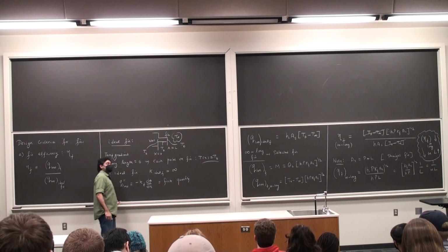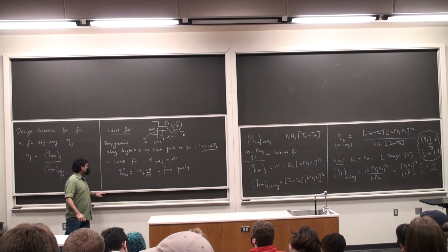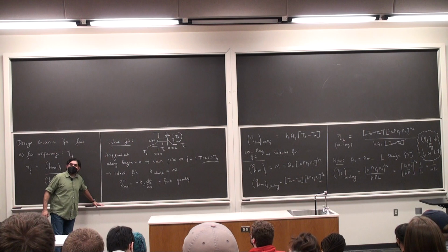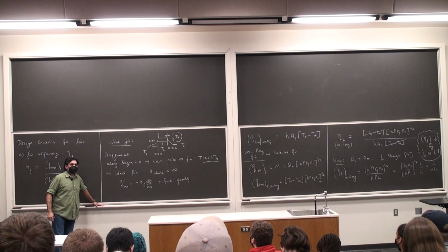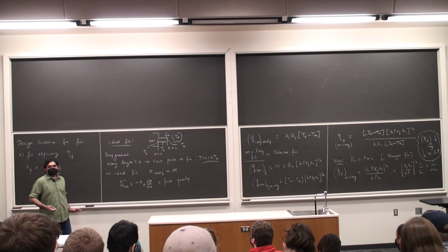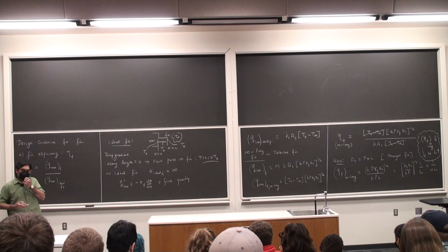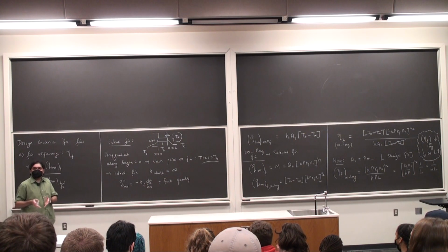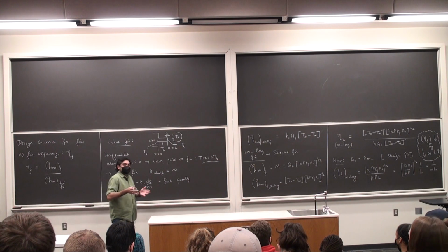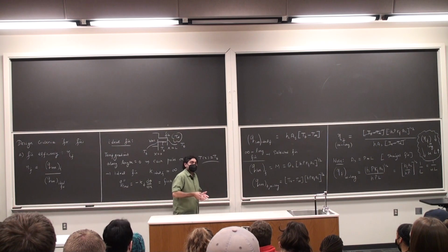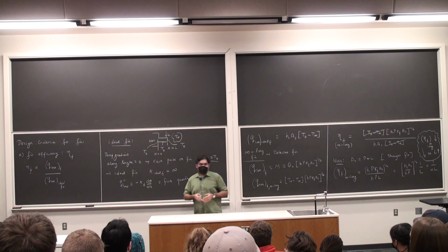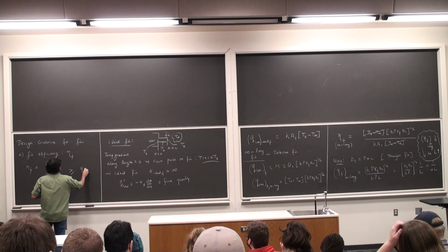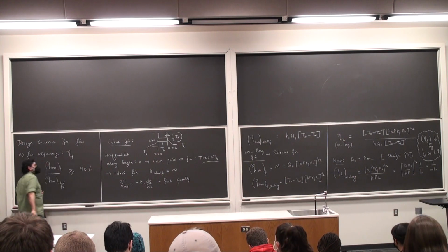So this is about fin efficiency. Normally, if your fin is less than 90% efficient, then don't use a fin. Most fins that are used for practical purposes have to be greater than 90% efficiency to warrant the additional cost, warrant the additional space requirements that entail the presence of a fin. Okay? So typically, this is a number greater than or equal to 90%.